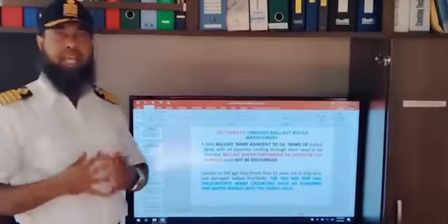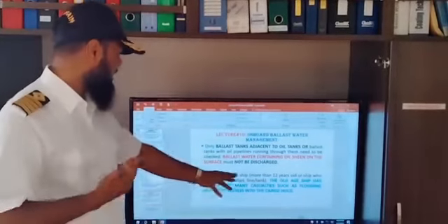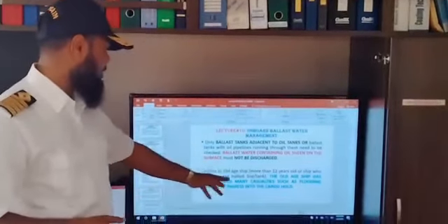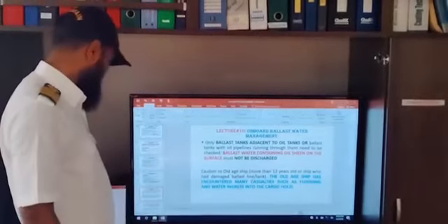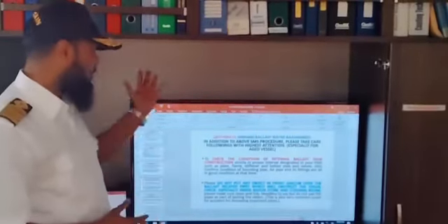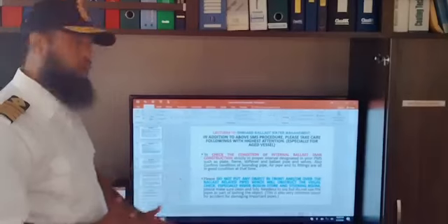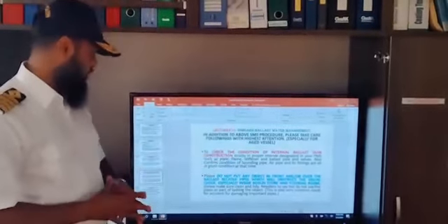And of course, aged vessels have the possibility of encountering many casualties such as flooding and water ingress inside the cargo hold. In addition to the above SMS procedure, please take care of the following items. Check the condition of internal ballast tank construction.